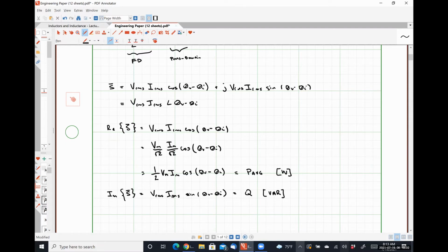That's correct. And you said that reactive power describes how a capacitor and inductor half of the time is supplying power and absorbing power. Mm-hmm. So when it's absorbing power, wouldn't that be part of the real power? No. It's all still reactive? Yes. So just because it's absorbed doesn't mean it's capable of doing work. All it's doing effectively is creating an artificial maximum for the amount of current that can be supplied.